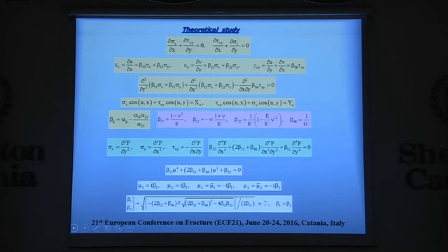And as usual, the equilibrium equations tell us there is a stress function related to stresses through this equation. So introducing these equations into the compatibility equation, we get the generalized biharmonic equation, and this is its characteristic equation, and these are the roots of the characteristic equation, the so-called complex parameters, purely imaginary numbers. Two of them are the complex conjugates of the other two.